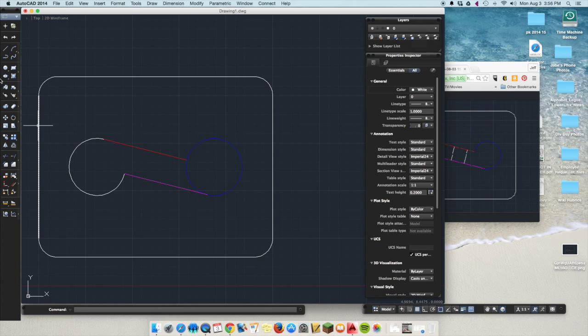Okay, and I hit escape, do it one more time on the other side, hit the trim tool, red line, magenta line, hit enter, that's my scissors. And then the small blue part of the circle here in between those two lines is where I'm trimming. I can hit escape. Okay? So now we're almost done.